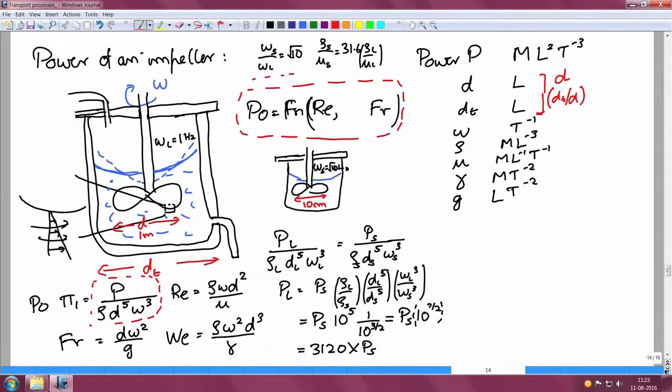I had also solved for you a problem of power of an impeller required for stirring the fluid, and showed you how you can reduce the total number of parameters, which is 8, down to just 4 of them based upon dimensional analysis. A further reduction can be effected based upon a physical understanding of what these dimensionless parameters mean in terms of ratios of different kinds of forces. For example, Reynolds number is the ratio of inertial and viscous forces; if Reynolds number is small, you can neglect inertia. Similarly, the Weber number is the ratio of the inertial forces and the surface tension forces. If that is large, you can neglect surface tension, and so forth. And we had used it for a concrete scaling problem.